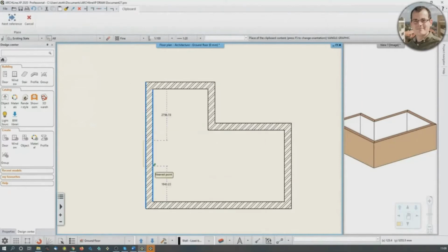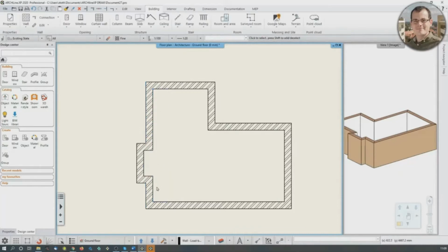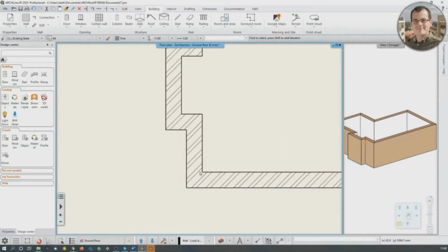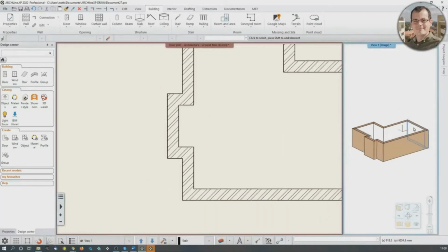And I just add. How do I add it properly? I mean, how do I position it from the wall corner? There's a tool for that, and I can do that by pushing the add-on to the wall, and I see where it says nearest point, and then I can just type in the value 1400 and this value will be submitted. So this 1400 comes from here. So okay, I think my drawing is getting together, but I have to boost it somehow.